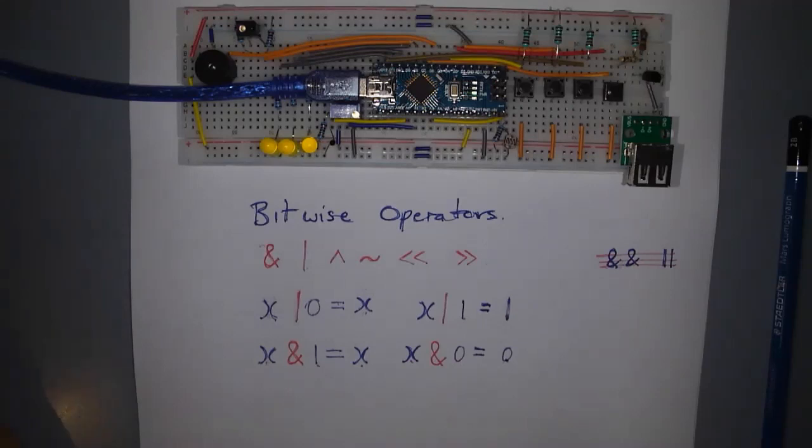But when we turn this into machine code by compiling this, we'll have a look at what actually happens. So if I open up the output files, I'll find the actual compiled code in main.lss, and I'll open that and I'll look for my show count function. Here it is here. Here's show count.